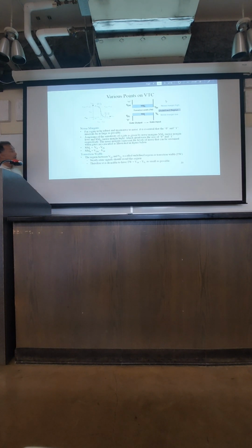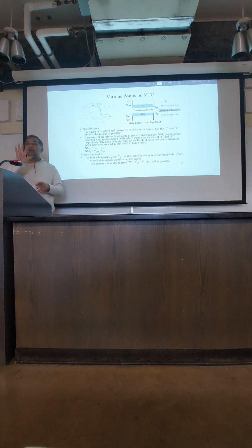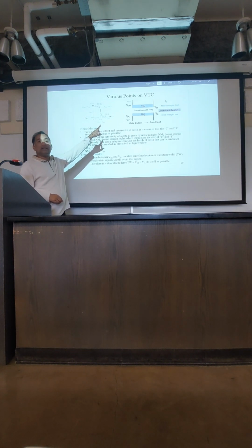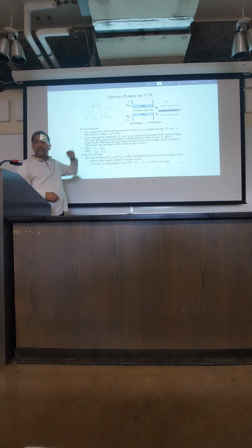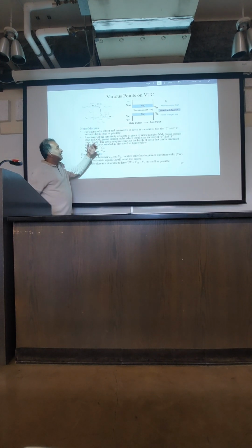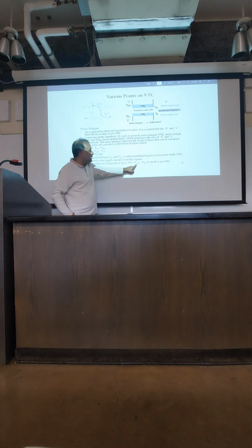So you see, noise margin is a dependent parameter, dependent on the 5 unique voltage parameters we talked about earlier. So every single performance parameter we are going to discuss later will be determined by those voltage parameters we introduced in the voltage transfer characteristics. Transition width, as we mentioned earlier, is that white gap area, the difference between VIH and VIL.